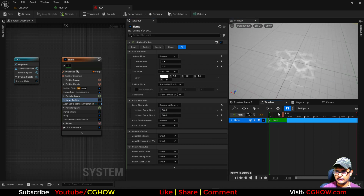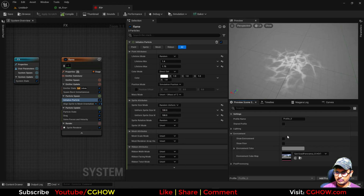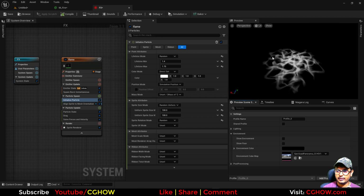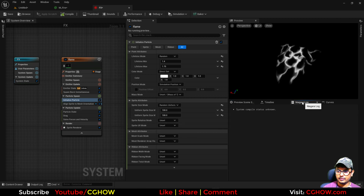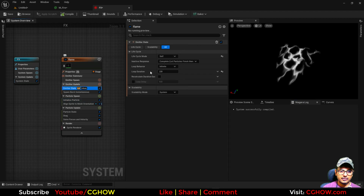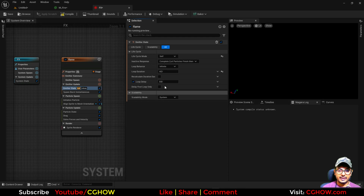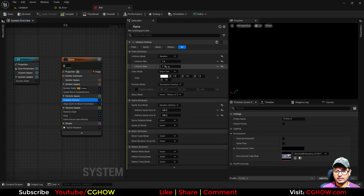So you got this, and let me just turn off the background and make this a little darker, and also hide the grid, and then turn off the random rotation. So you got this. First, let's make the overall 4.3, and then there is a 1 second delay, so this will be 3.3. Okay, and the life is okay.